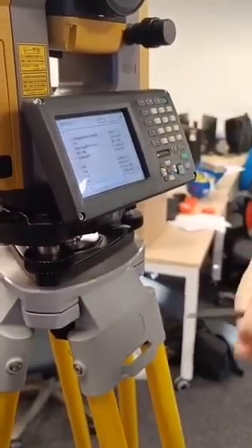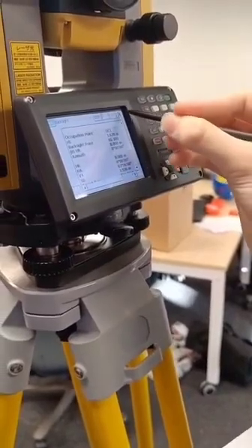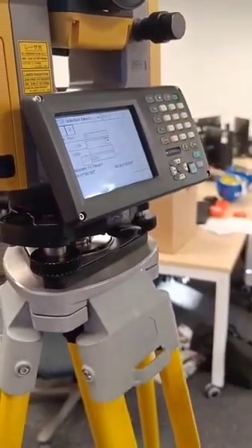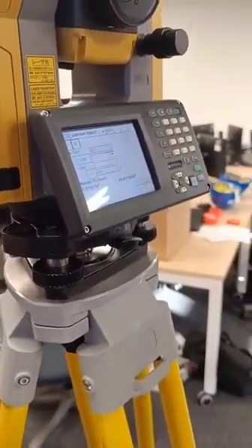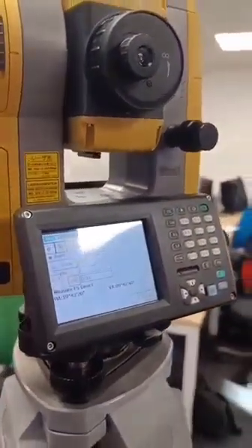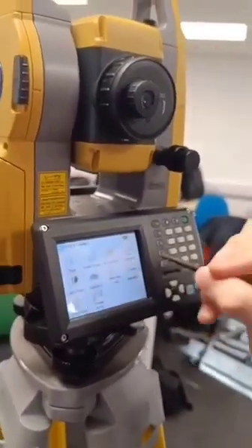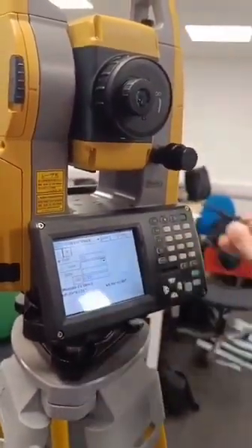And then just go back into PRG. Yep, tick, all good. This should come up, basically telling you confirmation of all your details. Yep, that's all right. Just close that. And now it's going to bring you into this menu where you can do all your points. So when you're measuring a point, you'll be on this menu. If it's here, just click on Survey Topo, and it brings you to the correct menu.